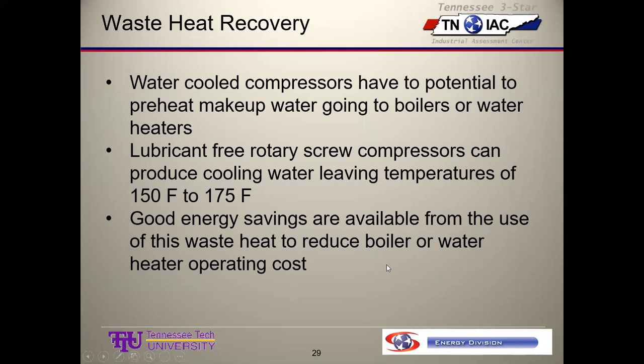They would simply treat the boiler makeup water, get it ready, and then it would flow through the air compressors, and that cold water would cool the air compressor. And so they would pick up a significant amount of temperature, probably 25 to 30 degrees, cooling the air compressor, and then they would take that water into the deaerator, and that would reduce the natural gas use on the boilers. It's really nice.